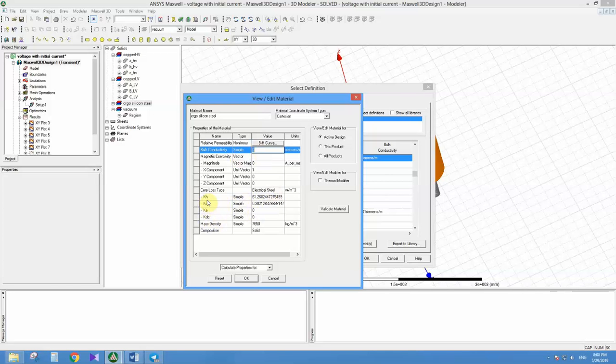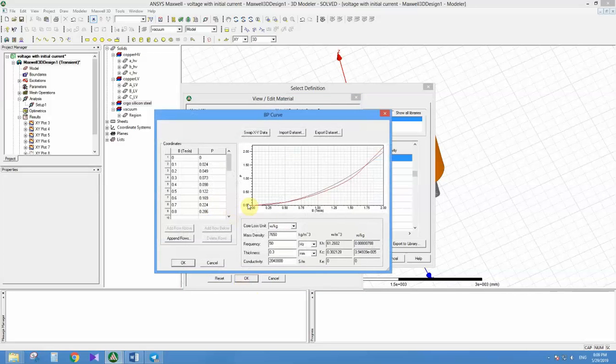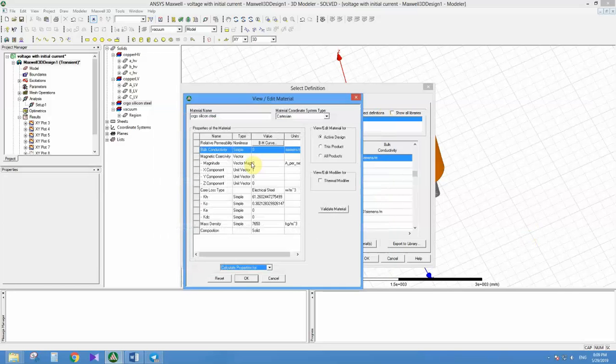go to help and see the coefficients, but if you want to use another core or calculate the core loss, you can come here and click on core loss at one frequency. I think you assigned it yourself, so you are familiar with this part. You can assign B in Tesla and power loss in watts per kilogram to calculate the core loss coefficient. Okay,